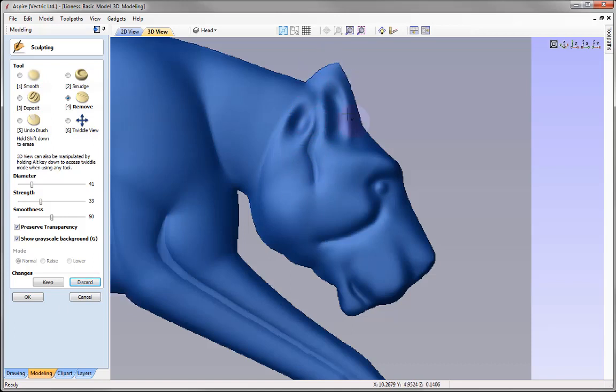And so now we can look at smudging the detail to create more of an ear shape. So let's use the smudge tool here. So here we'll go to the settings we've got. I might want to just decrease the strength there. And then we're just going to push the material to create that outer ear shape. Okay, so I'm just pushing. I want to just increase that strength. Pulling that up, and you can see we're forming that ear shape at the top there. I'm going to blend in the area where the head actually comes and meets the ear.